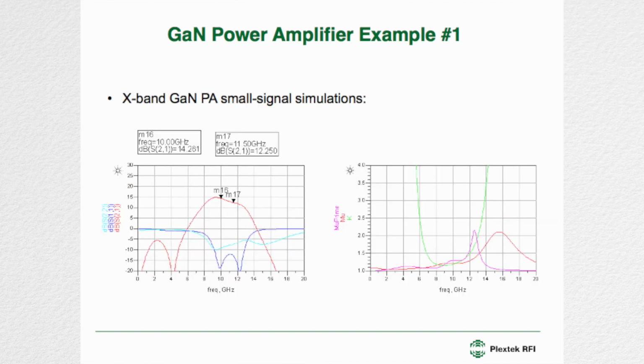And this is what we achieve. We have a good input return loss across our band of interest, across the whole of X-band, pretty much. Actually, sorry, not quite the whole of X-band, but from 10 to 12 gigahertz.